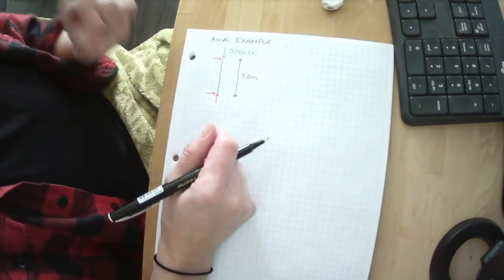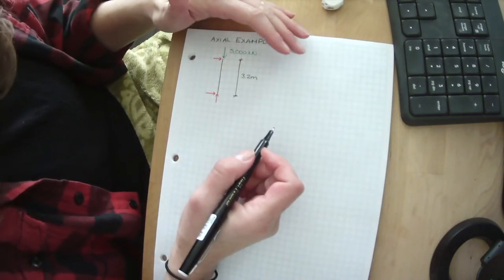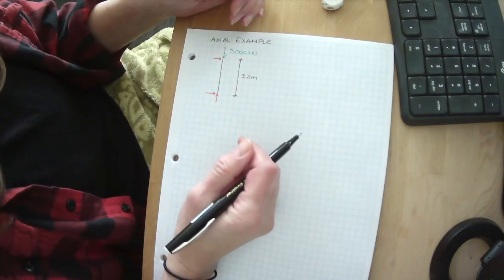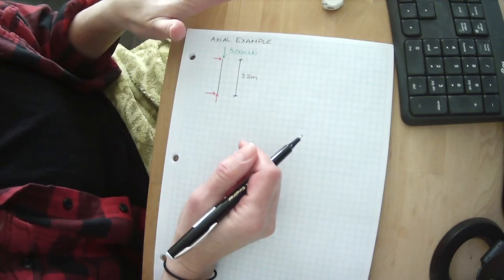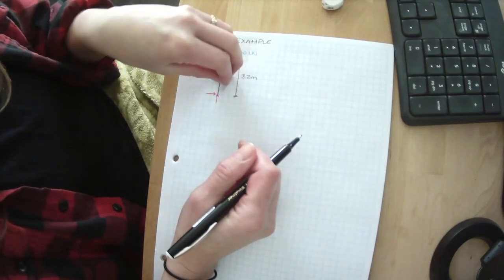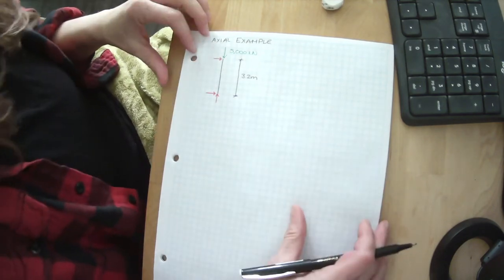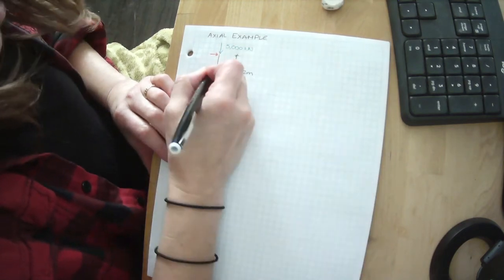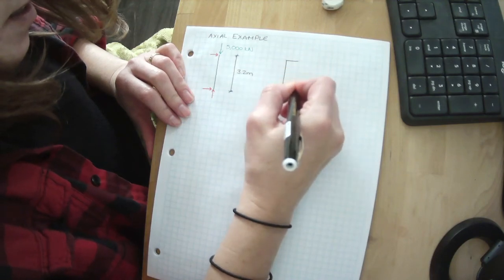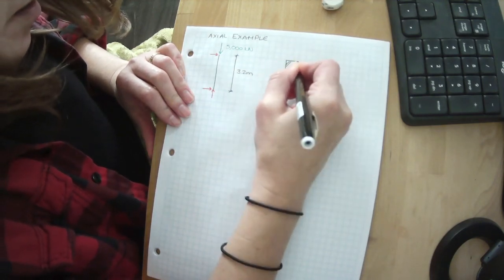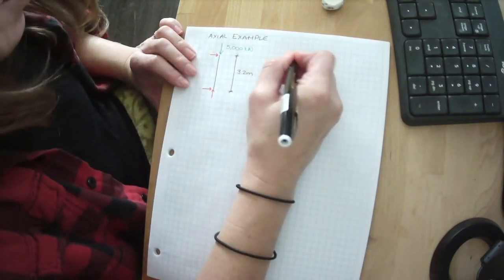So check one. We need strength, stiffness, and stability satisfied. We know our strength limit is 270 MPa, and our stiffness limit is, they've said, 5 millimeters of deflection. So those are the maximums. So we want to know what this object needs to be to meet those. We've met stability because we've got a reasonable free body diagram here. Okay, they have said that the cross section of this object, so there's our cross-sectional area. They've set this for us.